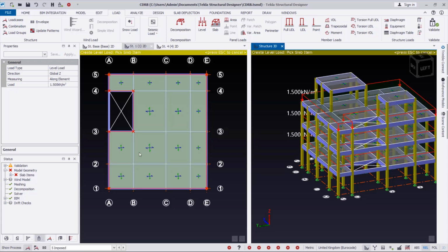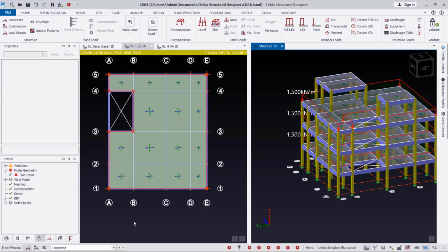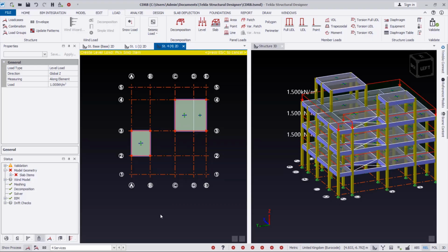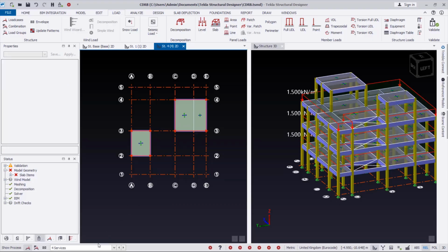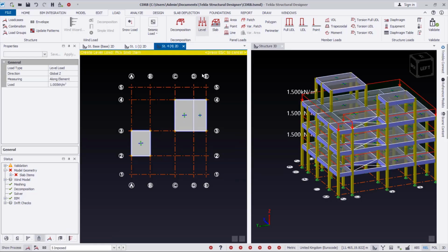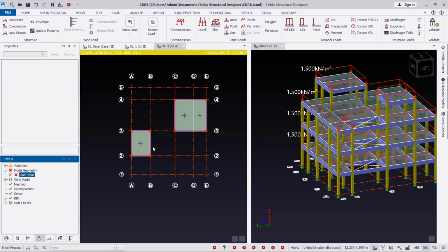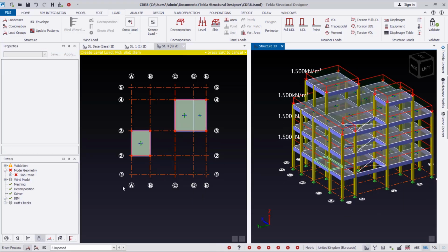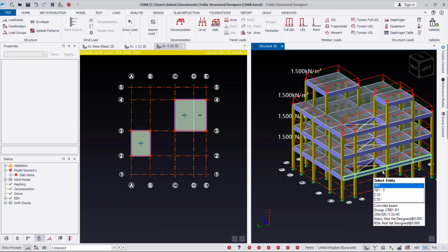You can see, so you go back to the ST4, but by then you have to escape this command, and then you click on the ST4 right here. Escape as well and change from this load case provisions to imposed load. All right, and then use this level load. Okay, at this point we are keying in 1.5, and then select on this slab to have it placed just like this.